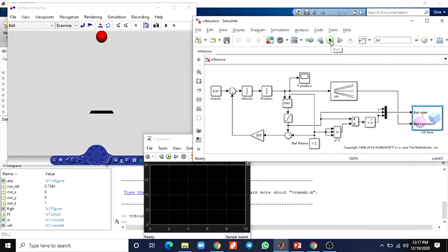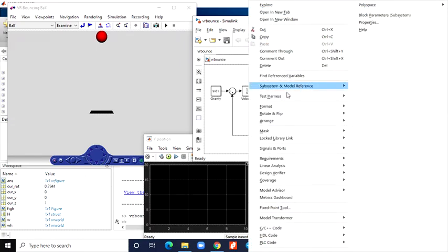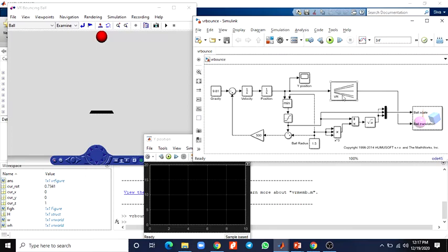Here this is the run button to run. Here these are the blocks available, like VR signal expander, from the Simulink library browser. Then another thing, these are commonly used blocks. The scope is used to display the output. Then you click run. This is the way to combine a virtual reality scene so you can control it by using MATLAB Simulink. You can create virtual reality scenes.